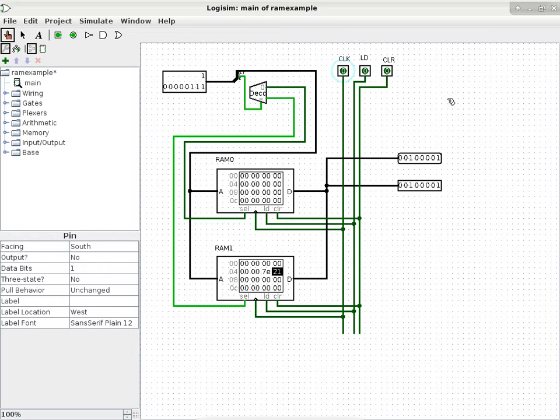So what about the amount of time the RAM needs in order to store the content? That will be the time from an edge to the next time the data line changes again. During that time, you have to freeze everything on the data bus, because the RAM chip is sampling the data bus and saying, I will take whatever is on the data bus to change the content of my chip. Is that okay? So all of this timing is very, very important. That's why when you look at a memory chip, a module, a DIMM, they come with all of those numbers, because each number specifies a particular part of the timing requirement.